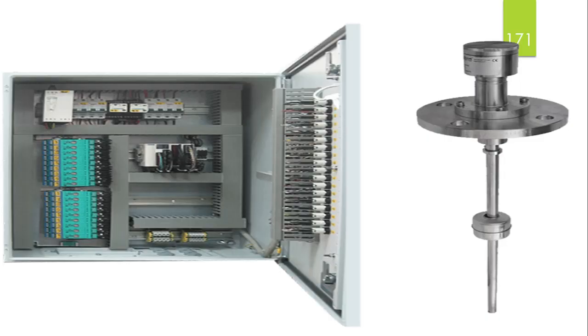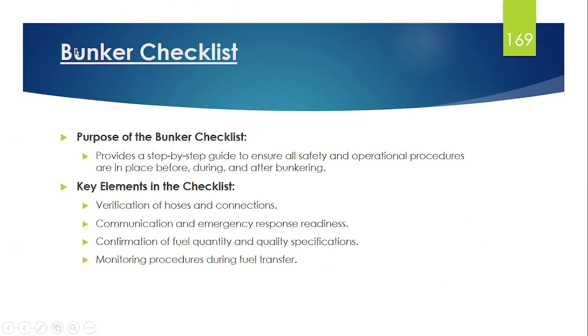One more time I'll tell you, the bunker checklist is a form of checklist which provides us a step-by-step guide to ensure that all the operational procedures and safety checks have been done thoroughly before taking the bunker, during the bunker and after the bunker. It means the bunker checklist is not a checklist which is completed only before the bunker. It is a checklist which continues before, during and after the bunker.